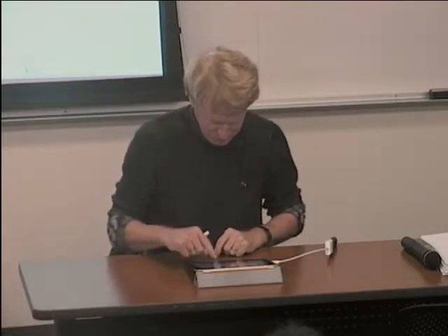This is actually something that people use in practice. If I want to have a gate that has a reduced swing, I want to save power. I don't want to swing all the way from rail to rail. I can easily take a threshold off from both the top end and the bottom end by putting those devices there. So this is actually used in practical circuits. It's not really something that we came up with to make life miserable for you.